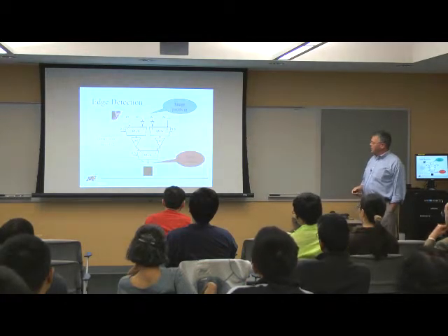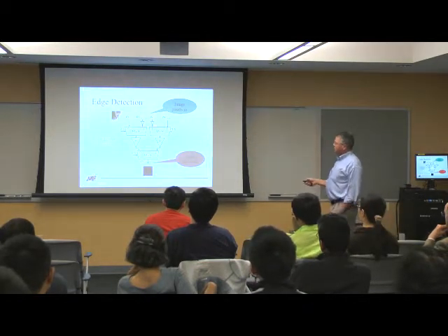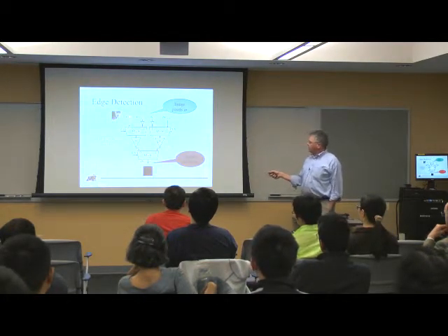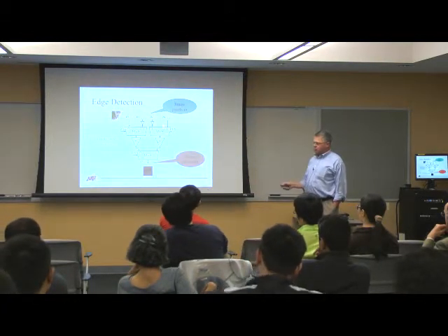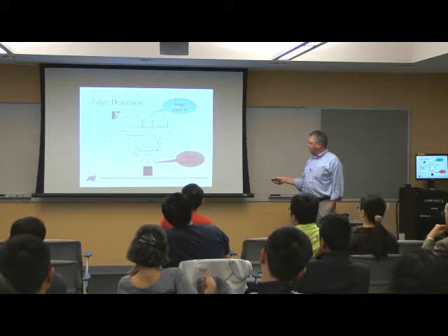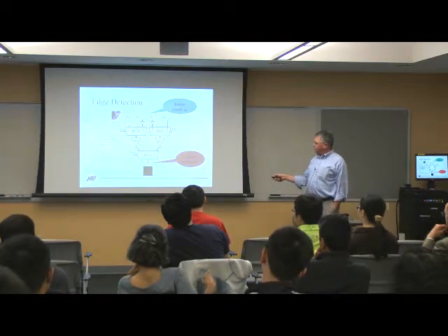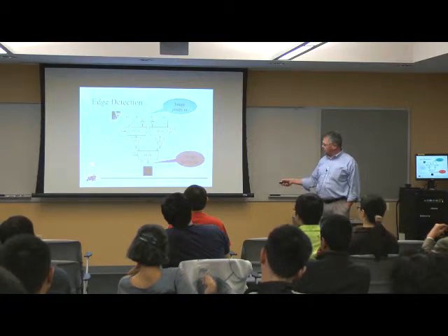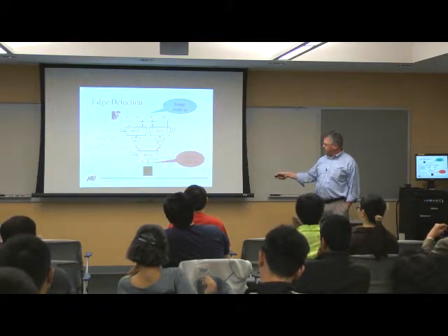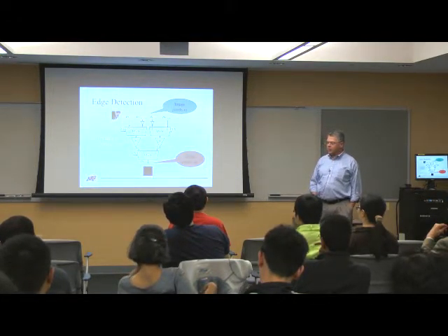What this looks like in the stochastic domain is that I've got the pixel and these adjacent pixels. This multiplexer and this multiplexer are doing a subtraction. This finite state machine implementation here is doing an absolute value function, which I saw here. And then I'm summing these two together here to produce the output.